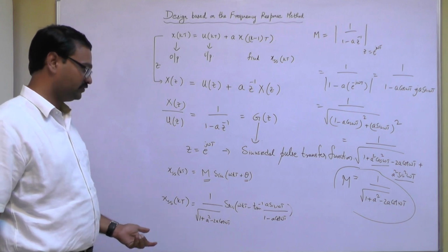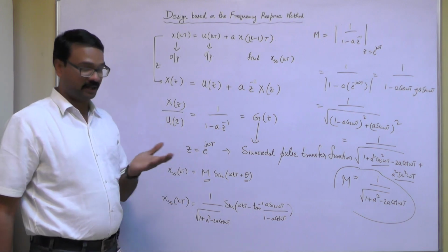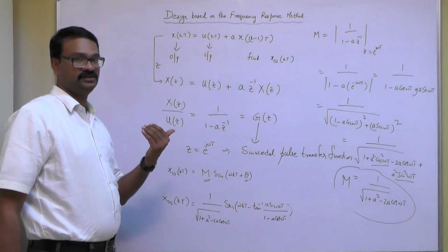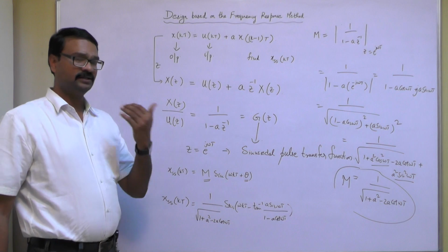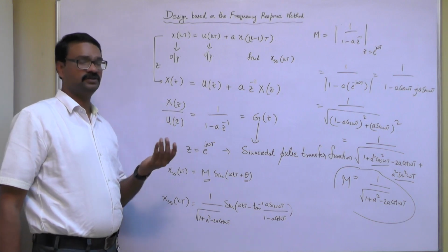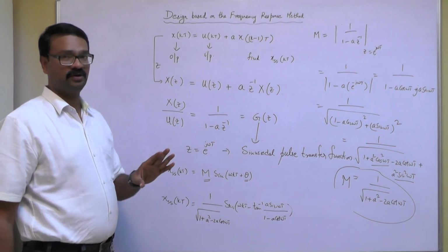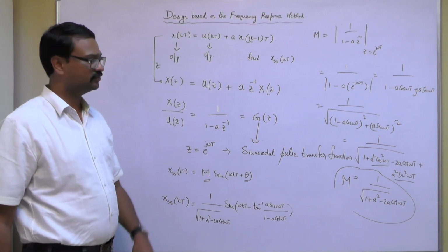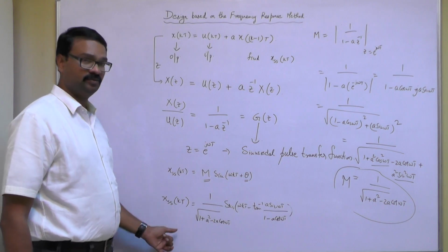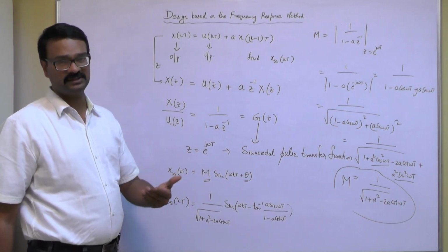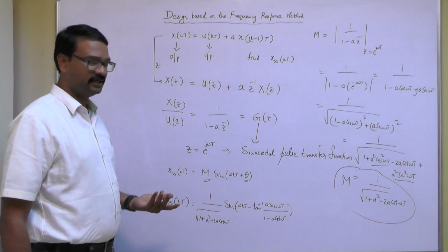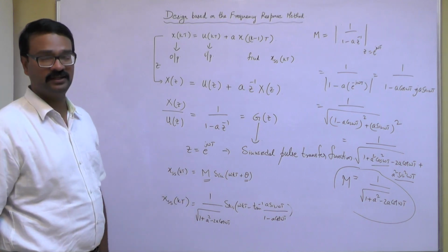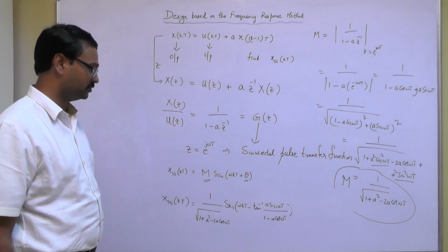Okay, after getting these values, we can use bilinear transformation and draw the Bode diagram to find the frequency response, just as is applied for continuous time systems. The same procedure used for the Bode plot there can be used for discrete time systems, where gain margin, phase crossover frequency and gain crossover frequency can be obtained by a similar method to that used in continuous time control systems.